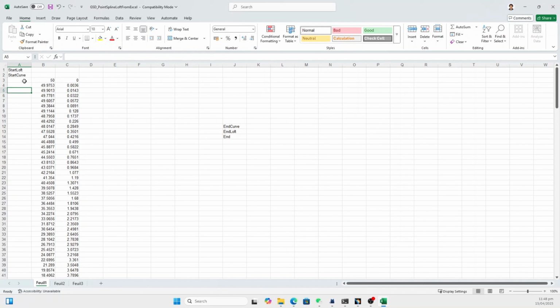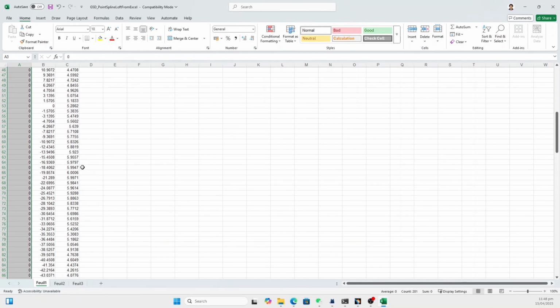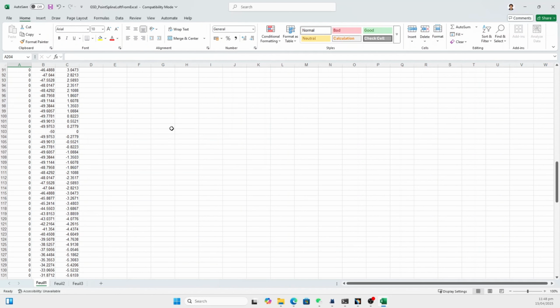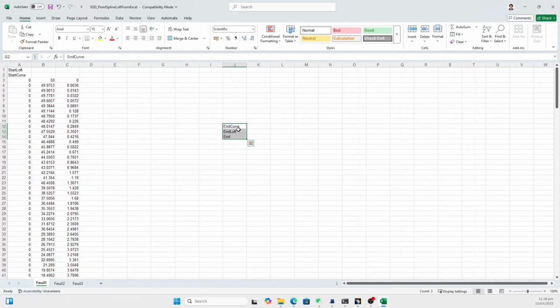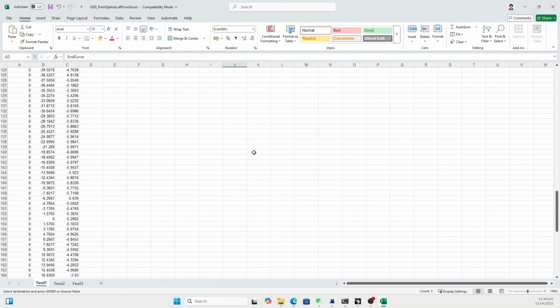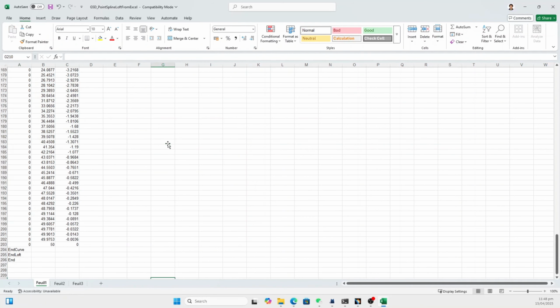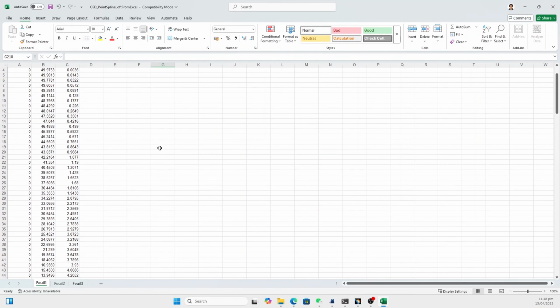So what I will do is I will just insert 0 here, and I will double click here so that all the x values are 0 until the last one. Now at the end I would just come and cut this one, Control X, and paste this one at the very end. So this is how it should be. This one is the one Catia will read.